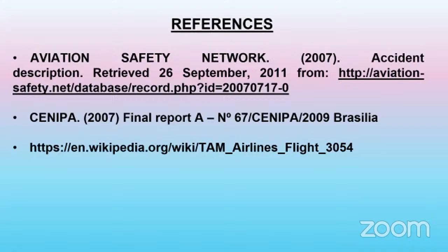Sir, it had a great influence on the accident. The runway was short, and there was aquaplaning, and also the lighting condition was not proper at the airport, and the grooving was not done. When the ATC controller told the co-pilot about this condition just 5 minutes before the landing, and the co-pilot told this to the pilot, he became a bit panicked. So maybe that also haunted his mind in taking the correct decisions.